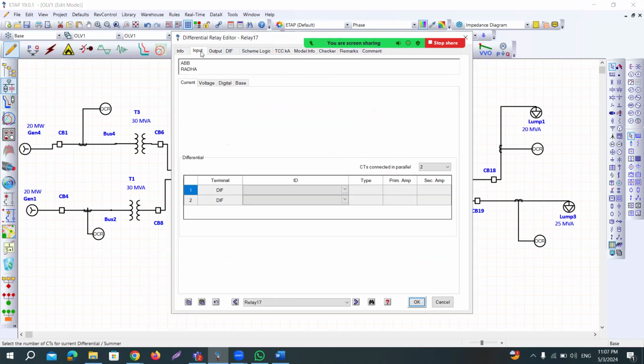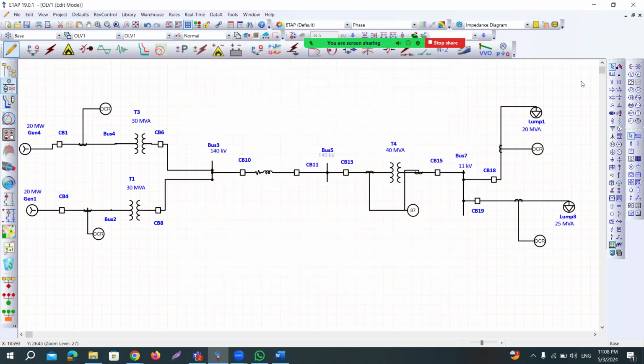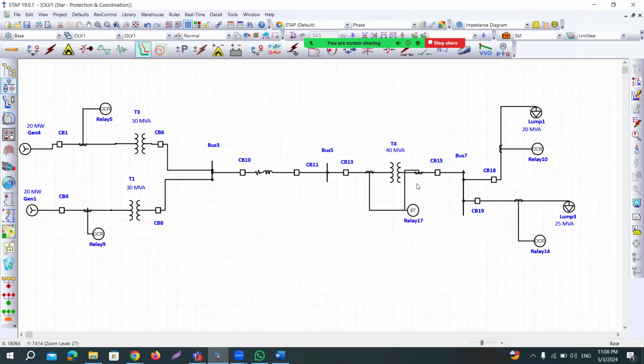I hope that everything is saved, the CTs 17 and 19. Now we want to apply a fault in between these 2 CTs. That means an internal zone. If the fault is in between CT 17 and CT 19, this should trip circuit breakers 13 and 15 in the first place. Okay, so let us see.